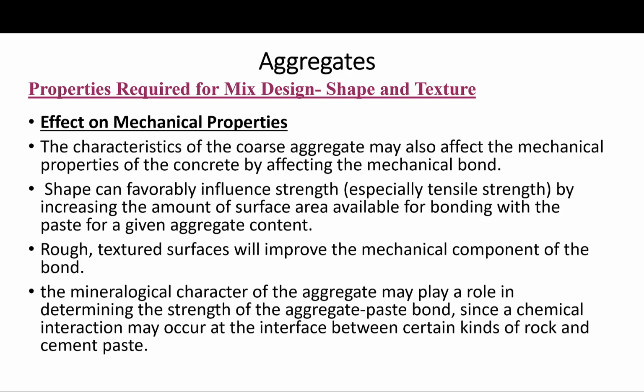It is also thought that the mineralogical character of the aggregate can play a role in determining strength of the aggregate-paste bond, since a chemical interaction may occur at the interface between certain kinds of rock and the cement paste. And again, that's something that should be investigated.